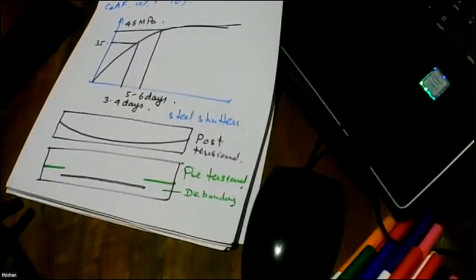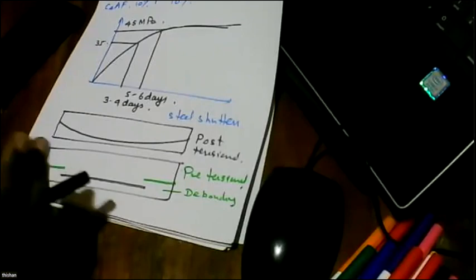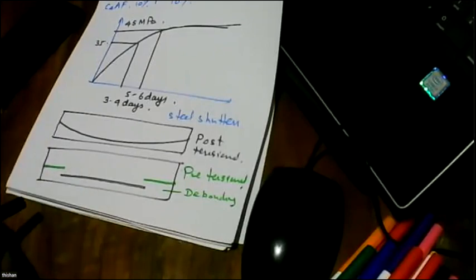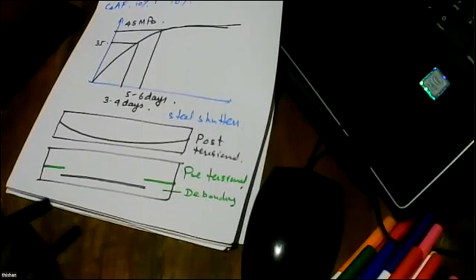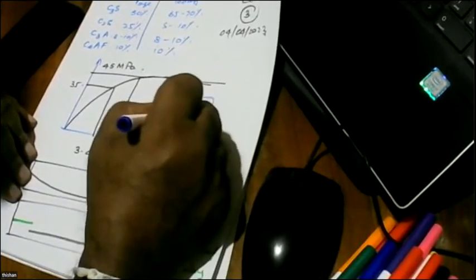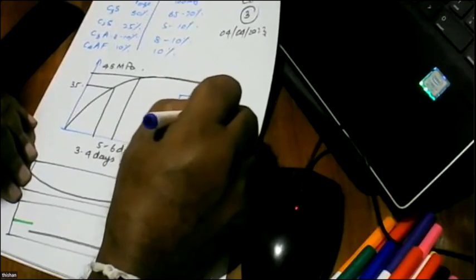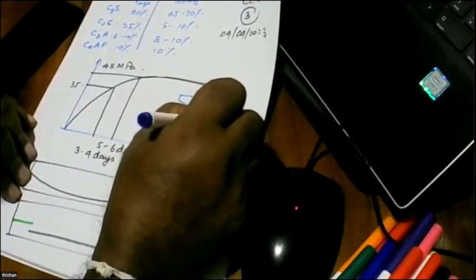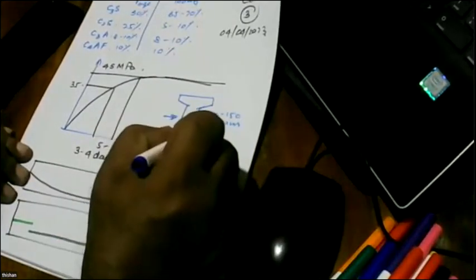If you look at today's scenario, all this is possible because we have cements that gain strength very fast, and also because, compared to the earlier situation, we go for very small sections. Again, there's a minimum width that we can cast, something like 120 to 150 millimeters, because we can't reduce it any more, and we get a section like this.